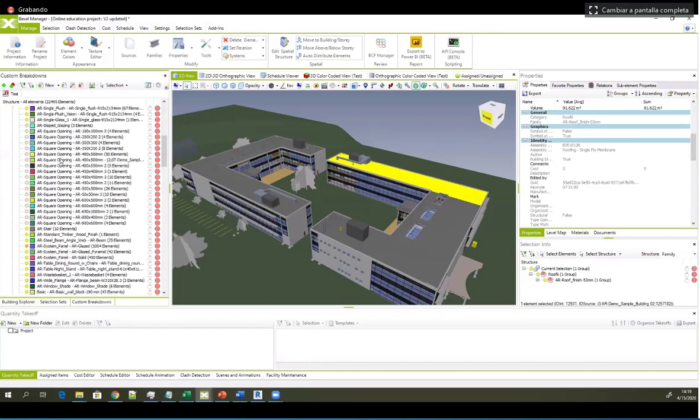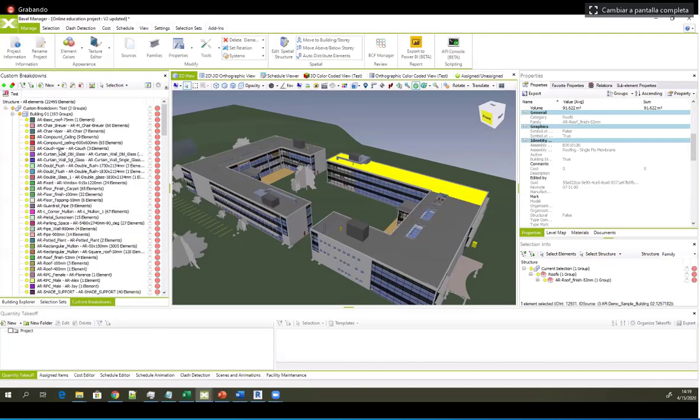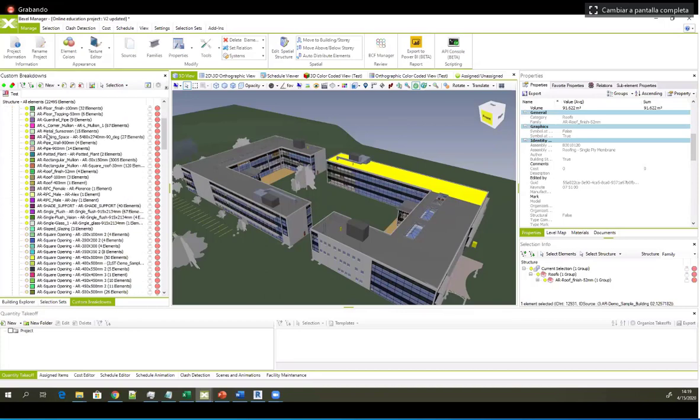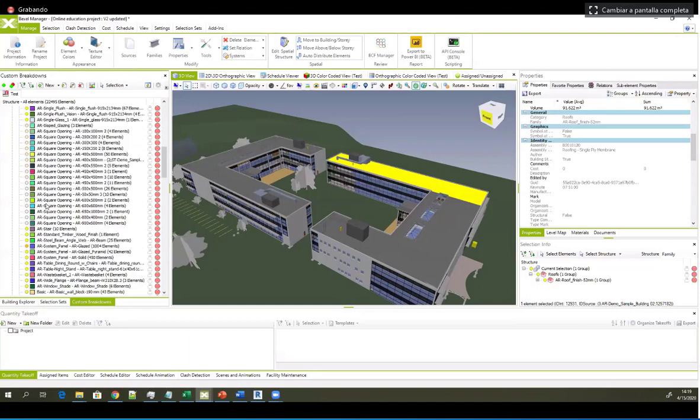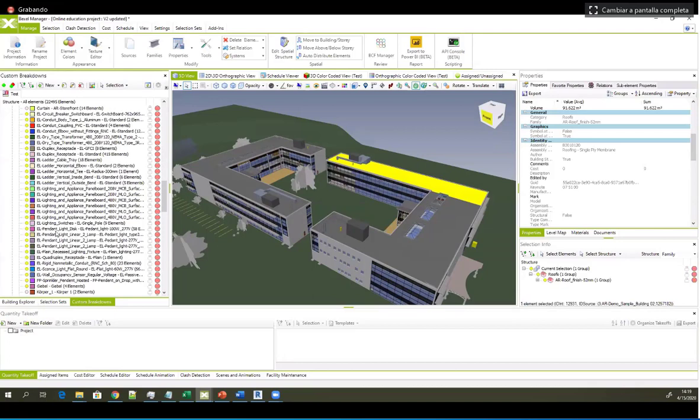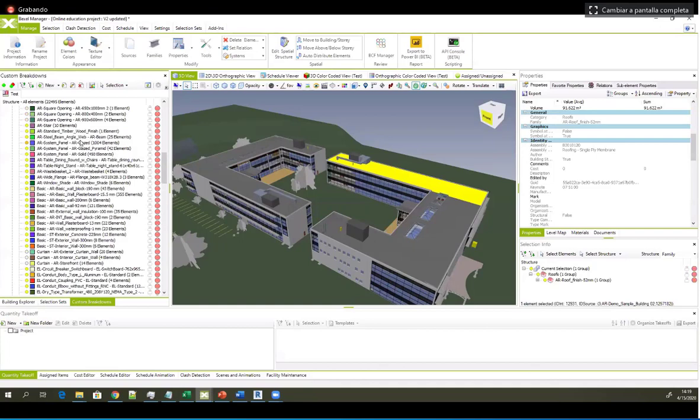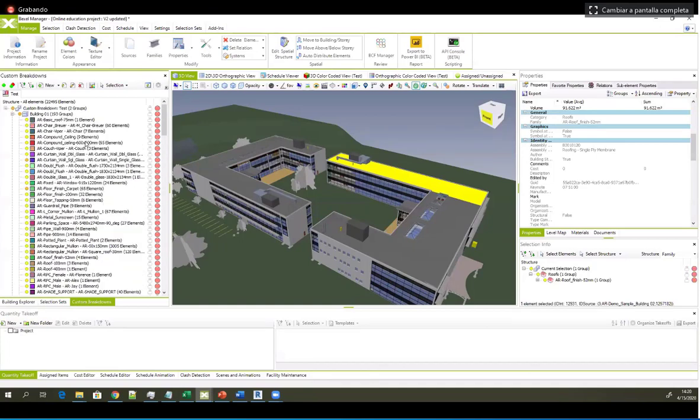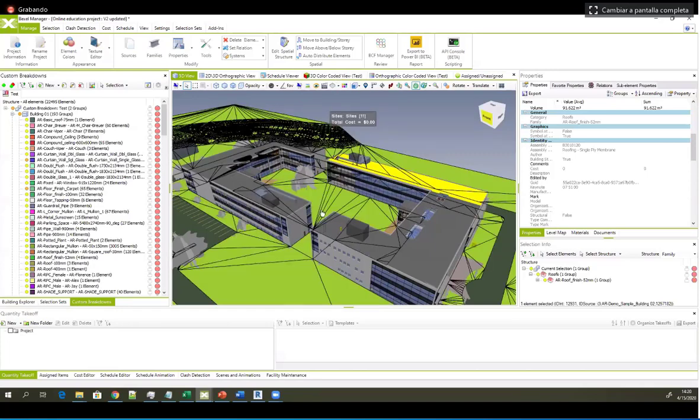So an additional way how you can do it here is just segregating the elements based on the family or based on the name. And here you can track if your elements have a specific, I don't know, naming convention or prefix or suffix to their name according to the naming convention. And of course, since we used colorizing the elements, this is where we can use a different view for showing the B-model elements according to this way of colorization.